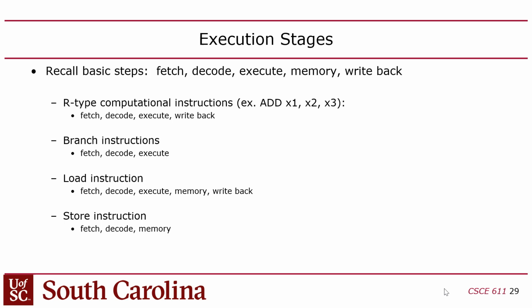That's really what we should do, but we decided to simplify things to 3 cycles in this class. We're going to do a 3-cycle pipeline. Now you might say, how do you go from 5 cycles to 3? Well, we just merge together the middle 3 cycles: decode, execute, and memory. Of course, memory doesn't exist because we don't have any memory instructions. So decode and execute are together. We just merge those into one stage called execute. Is that a good idea?